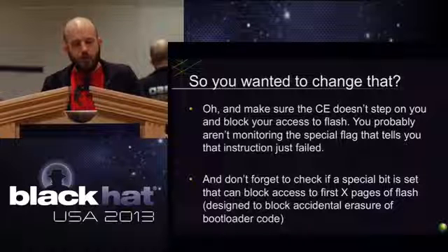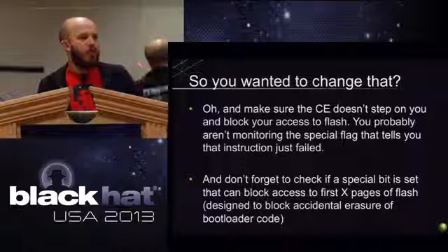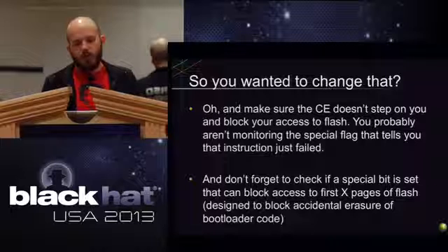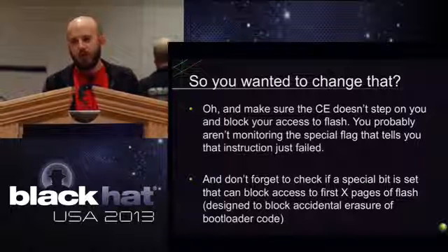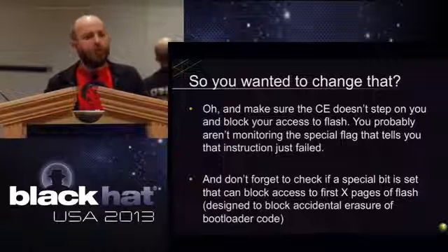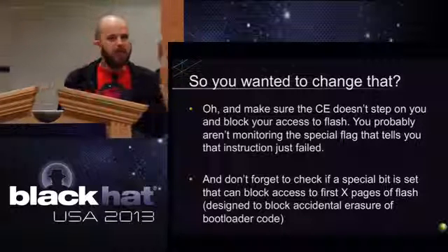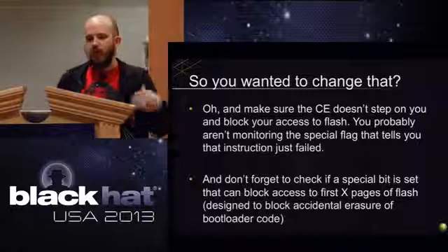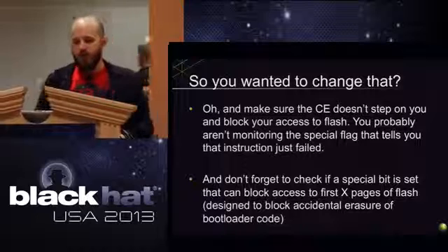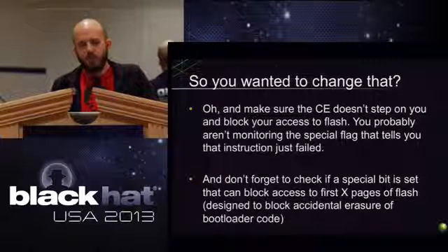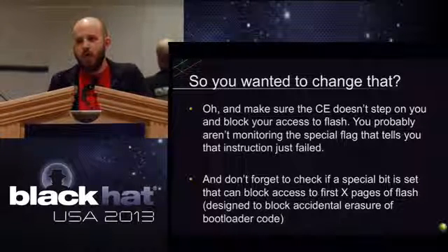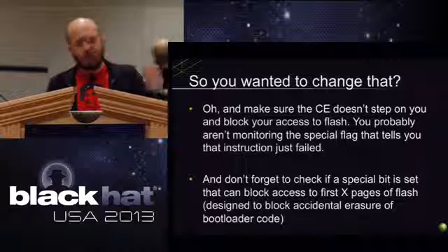It has a way for you to set certain bits that say turn off the first, you know, X pages of flash from being able to be mass overwritten. That would typically be where you would store boot code, for example. Something like a failsafe, or the code that loads everything else. You put that there, and you never want it to be overwritten. But it's just a bit, so it's not a security feature. You can just go in and change it if you need to.